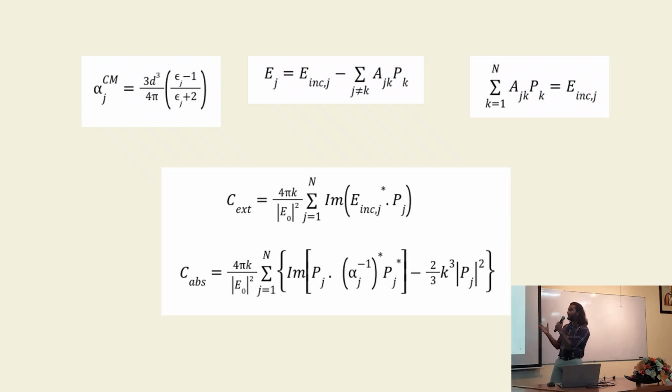Then the electric field at any point inside the volume is calculated using the incident electric field. This happens as if we are sending light from one direction towards our object and the light gets scattered around. That incident radiation electric field is used, and the polarization is calculated from the electric field. So at the end it solves this equation and finds the electric fields and the polarization.